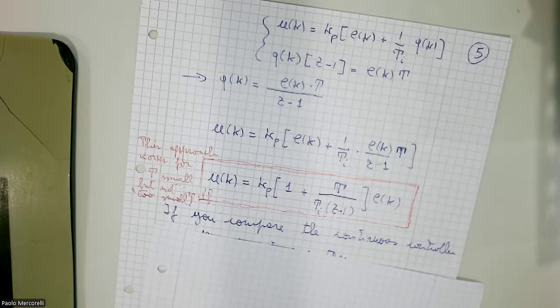If you remember in MATLAB, we have the block Z to the power of -1, or 1 divided by Z. Yes, the name is Delay. In fact, when we realize the model in discrete form, we use this 1 divided by Z. Sometimes we also use it for a different goal, in the Kalman filter and so on, but it's a delay.